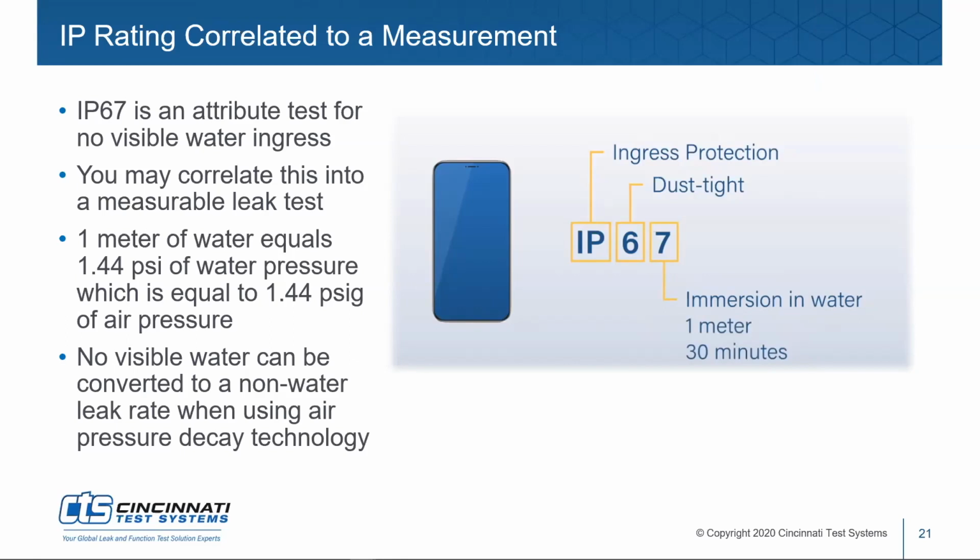So that if your pressure falls below a certain set point, then you know you have a gross leak in the part. That makes sense. Yeah, and this type of testing actually started years ago with ECUs, engine control units, under-hood computers sealed completely in a die-cast housing, and really has morphed from that to IP67 or IP standards.